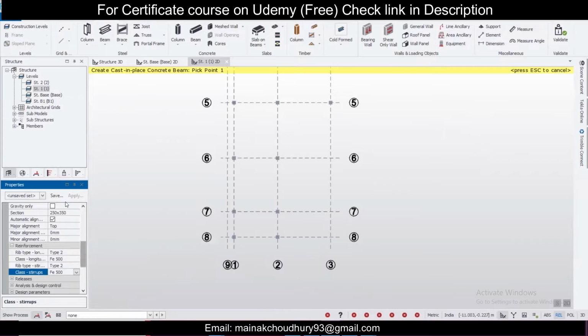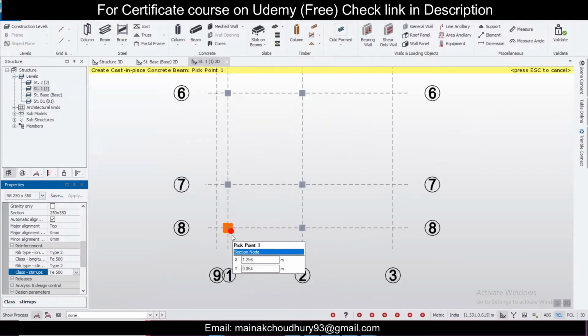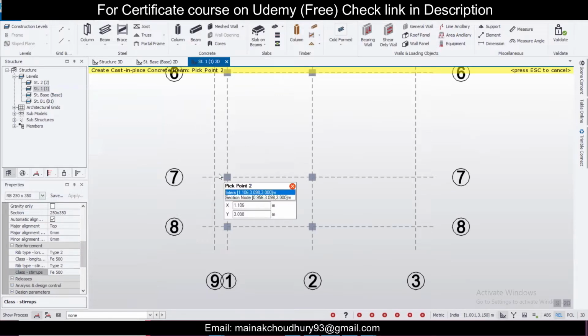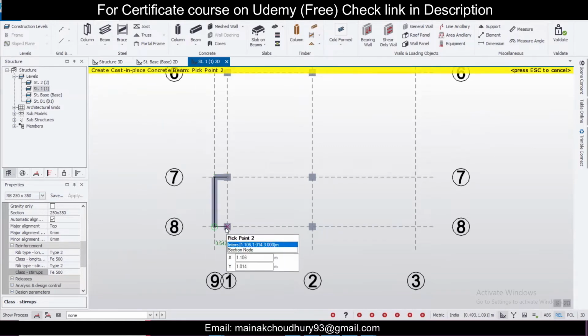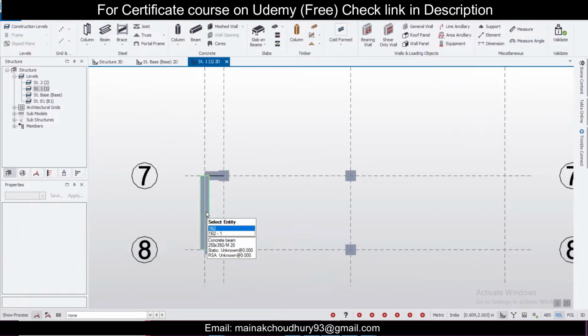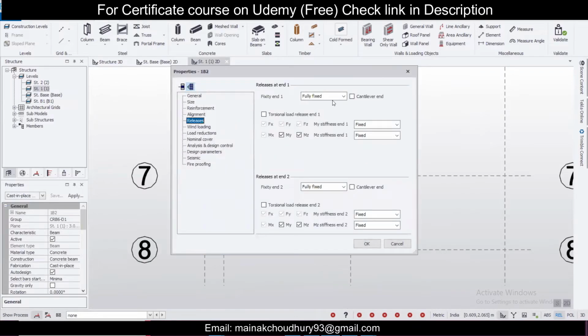For the roof beam portion, first of all, we're going to select this RB 250, and there is a secondary beam here because there will be a landing, so there will be a beam above this too. Like this will do, and like this also will do. Here, this particular beam, click on escape, double click and go to releases. Both the ends are pinned, make this pinned, right?